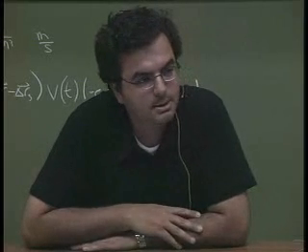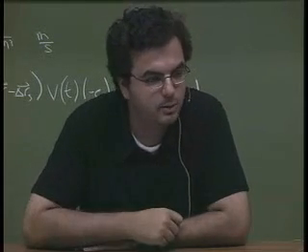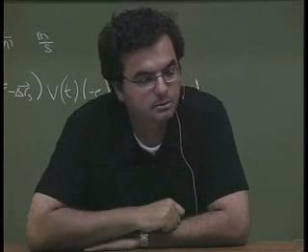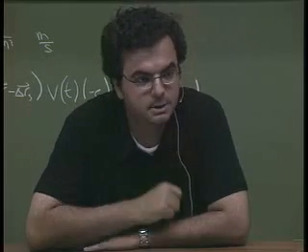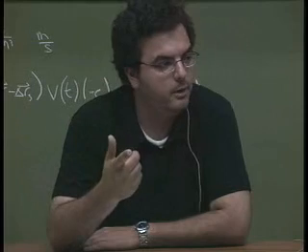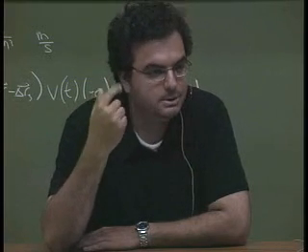And it's very interesting that the human ear actually is a nonlinear system. It actually is sensitive to jammers. So if someone comes into the room and plays a tone for you, let's say at 100 hertz, and you're listening to that tone, and then someone turns on a second tone, let's say at 200 hertz, you'll hear two distinct tones. But as they keep increasing the amplitude of the 200 hertz signal, there'll be a point at which you'll say, oh, you turned off the 100 hertz tone. I only hear one tone now. And the person will say, no, I still have it going, because there's actually, let's say, cubic nonlinearity in our ears that acts like a jammer.